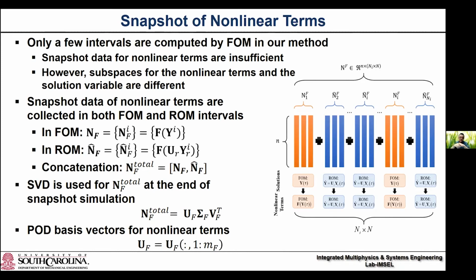Then we will write through the nonlinear operator. We will get the snapshot of the nonlinear terms, and then in the reduced model interval, we will first reconstruct the solution in the full domain, and then write through the nonlinear operator, and then we will collect this reconstructed snapshot of nonlinear terms, and then we combine them together, and then we can perform a POD at the end of the snapshot simulation. Once we have this POD mode for the nonlinear term, then we can do